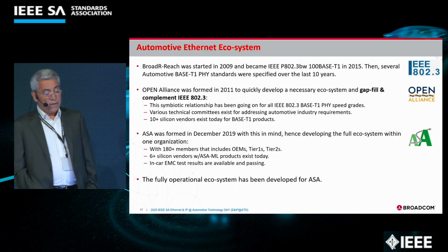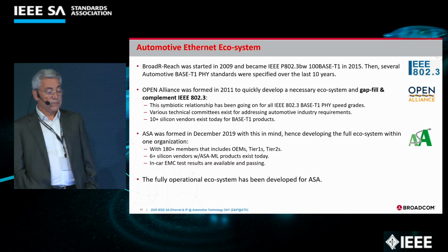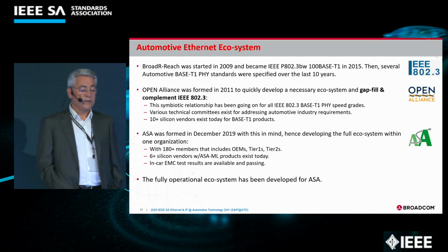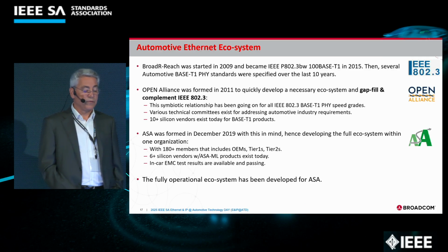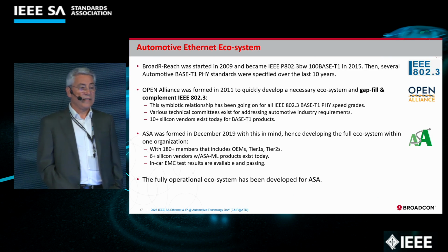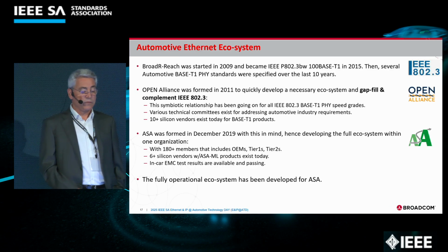So one important factor is the automotive Ethernet ecosystem. The Open Alliance was formed to quickly develop a necessary ecosystem and complement 802.3 BASE-T1 PHYs. Various technical committees exist for addressing automotive industry requirements and needs. There are today at least 10 silicon vendors supporting BASE-T1 PHYs.